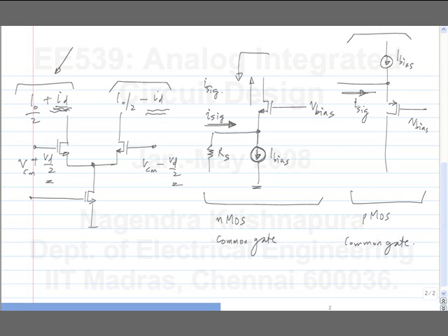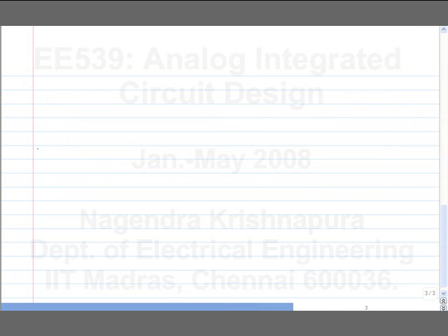Now, if I look at what I have, the NMOS differential pair, I have the bias plus signal right away. So I can use the same current to bias this. Okay? It's just a matter of convenience. Is it okay? So that's what I'll do. So let's say first I'll choose to use the NMOS common gate.